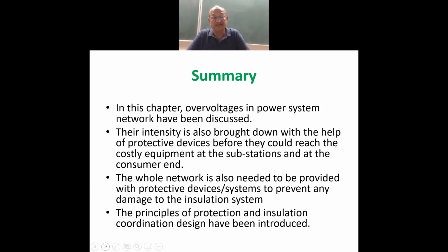Accordingly, in the laboratory techniques, every gadget has to be tested with lightning impulse, and for many of them the requirement today is also for switching impulse voltages, because an insulation would withstand a much higher lightning impulse voltage as compared to the switching impulse voltage.